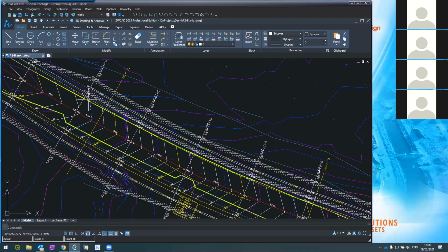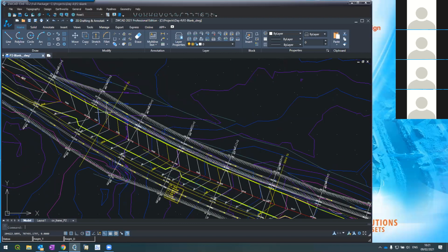Therefore, we will have to create our own transition. I will take a transition, it's my decision, 20 meters. I will start the transition 20 meters before the tangent point and end 20 meters after the tangent point. This is my decision. I'm using a slope of 2.5% each side. What I intend to do is a transition from -2.5 to 2.5 on one side, to the left. I hope this is understood. But if not, very soon I hope you'll get it.